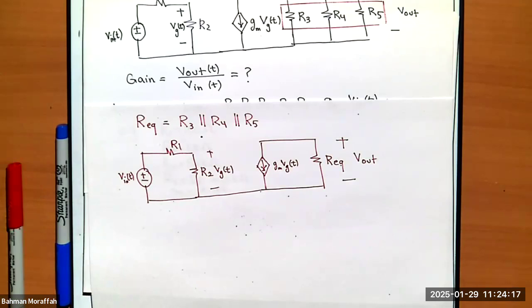We have a circuit with a dependent source. If you guys recall, what we said about dependent sources was we always treat it like a regular independent source, but since its value depends on something else in the circuit, we always have to obtain that value somehow in the circuit and then plug it into the formulas that we have.